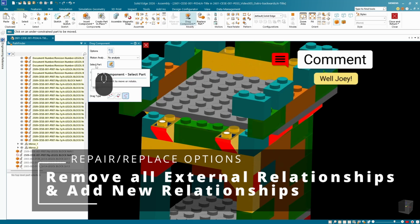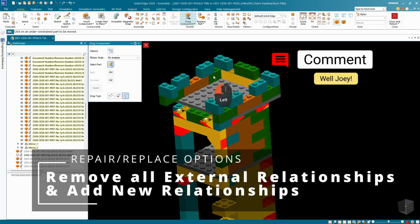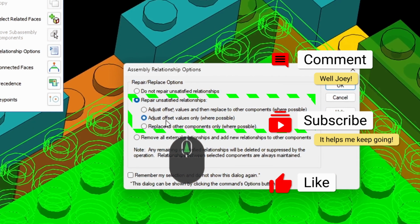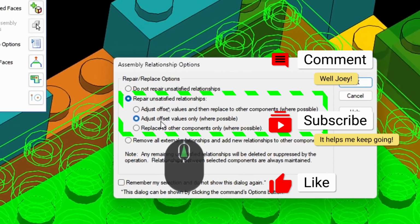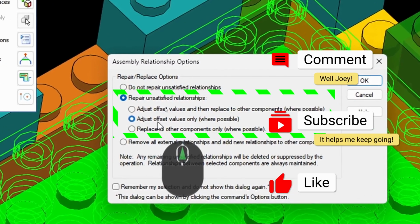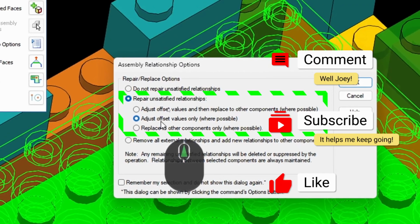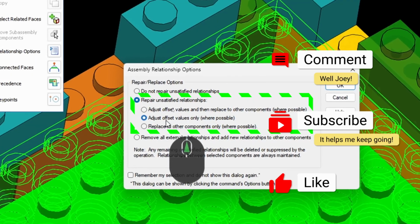We are at the select part step of the drag component command. It won't let us select the plate or the parts above it because they are fully constrained. It will only select a part that isn't fully constrained. All of these parts are fully constrained, so we can't even select them to move. We didn't look at the different repair unsatisfied relationships options within the assembly relationship options dialog box because this wasn't a good example to use these. If you would like a video on them, let me know in the comment section and I'll add it to the to-do list if there is enough demand.